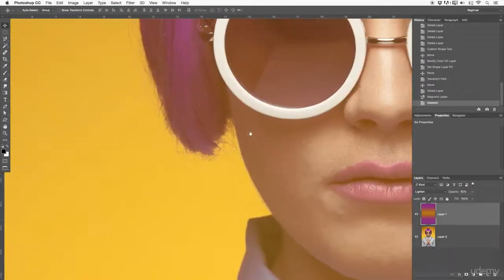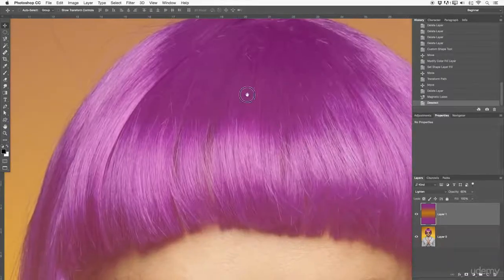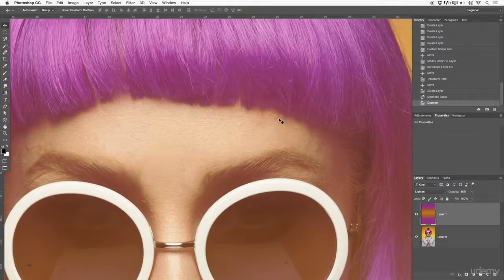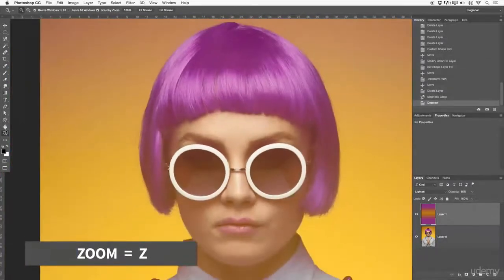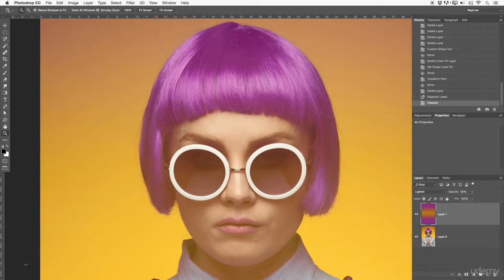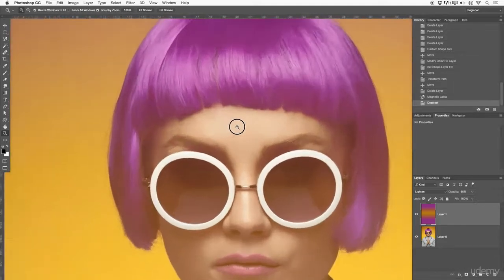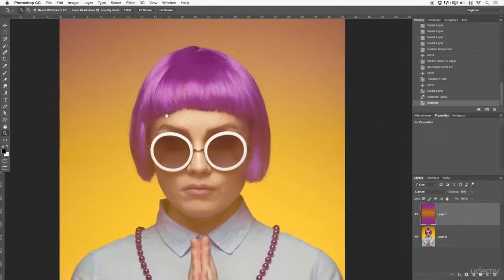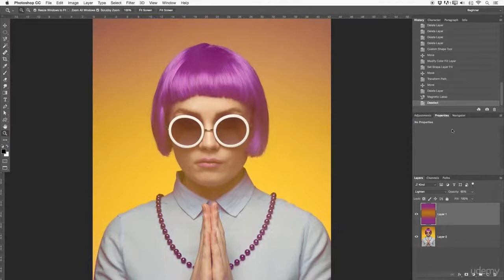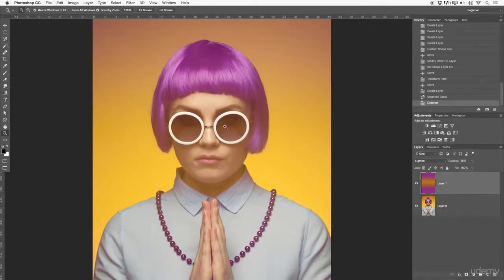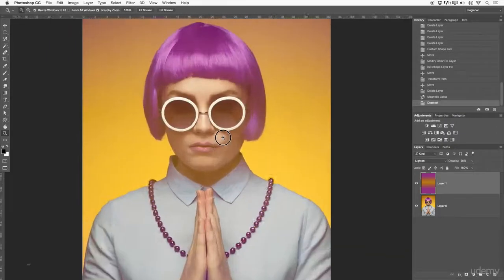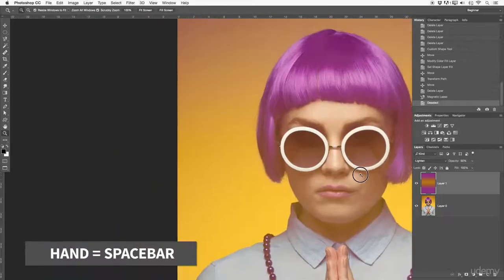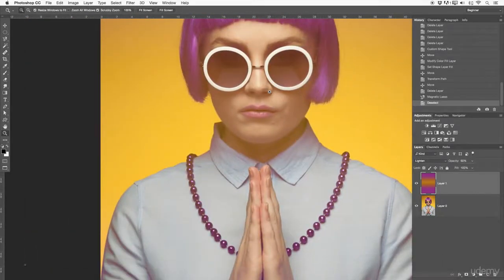Let's get out of the selection and just zoom around a little bit in our picture. Let's just move around. So again, when you work with your image, press Z for the zoom. Again, right away, you also see now the zoom is selected. So press Z, click with the mouse and keep on dragging. Drag in or drag out in order to zoom in and out. If you are not familiar with this and if it's struggling, use the navigator over here. For the beginning, navigator should be good, but also the zoom, it's not too complicated to work with. And if you want to walk around in your image, hold spacebar and move around. These tools you should right away memorize because Z is your friend and spacebar too.